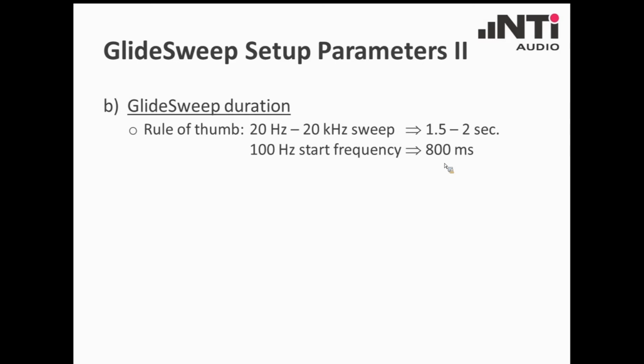And then after having accomplished the first measurement, having received the first test results, you can go to the next stage, and that is the optimization of this duration, saying you can now stepwise cut it down, minimize it with the trial and error approach. That means you would repeat the measurement and compare the results with the initial status and the new shorter time. And as long as these results correlate, are identical, you can further go down and even speed up the test more and more, up to the point where the results start to deviate from the correct status.